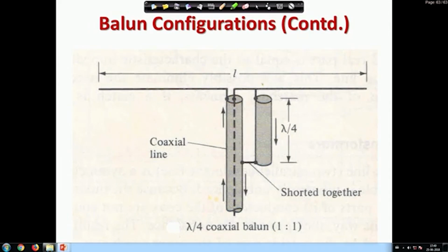So, without a balun, the common mode current increases. To reduce that, the balun is used, and if you put the balun, the antenna can radiate or receive quite efficiently. If you remove the balun, its efficiency will drastically go down, and you can check that: just remove the balun and see the reception quality on any TV will be poor, because the balun improves the differential mode characteristic. It is something like what we call CMRR.